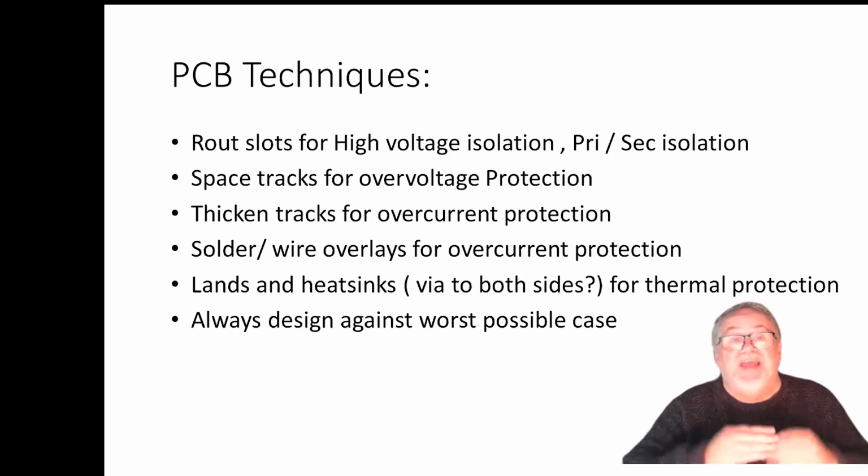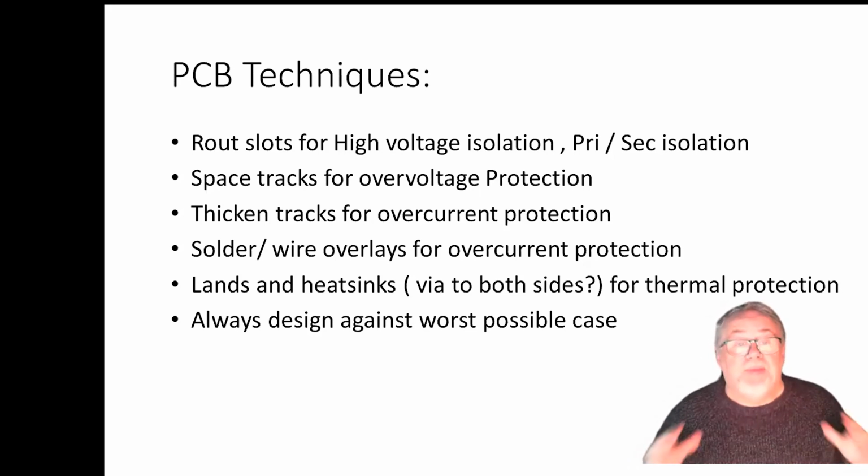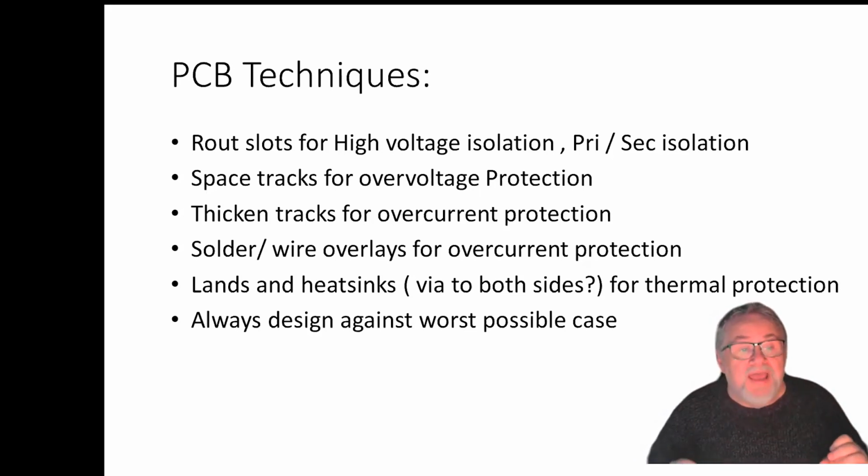You space tracks far apart to keep voltages from jumping over them. You make tracks thicker to make them carry more current. If they're not thick enough for you, you either put a fillet of solder on top of it to make the track thicker, or you even put a fillet of wire on top of it to make the solder thicker, to get more current onto it.